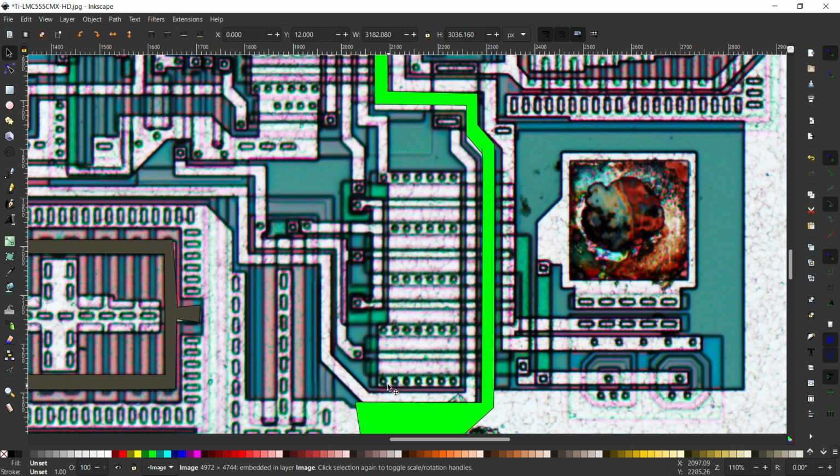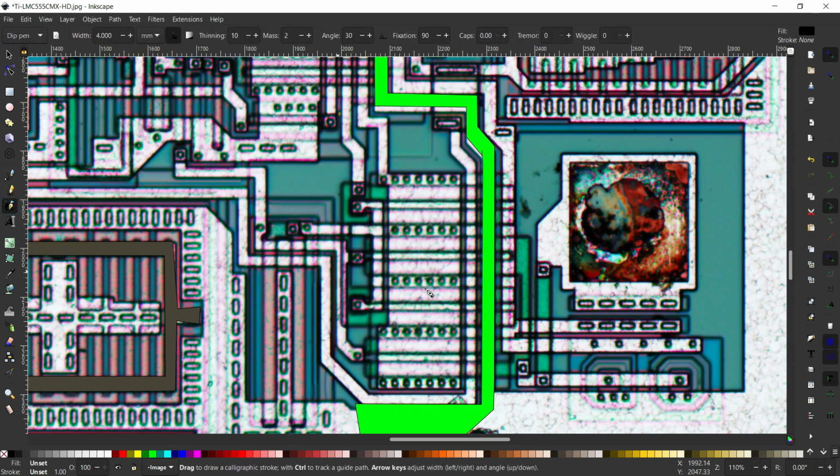See the dotted circles whatever you are seeing, those are all vias, okay. Everything, whatever square boxes and rounded shapes you are seeing, everything is a via. And the straight lines you are seeing here, let me draw some lines. These straight lines are the gate connection. Because it's a comparator, it has a gate signal and it has source and drain terminals. So these straight lines I have highlighted are all the gate connection. Okay. Then in between the gate connections, we have source and drain regions.